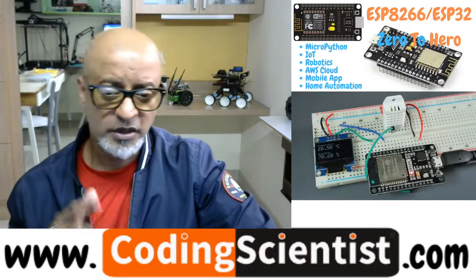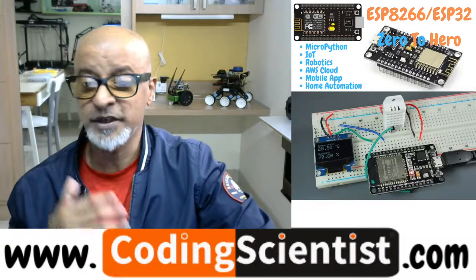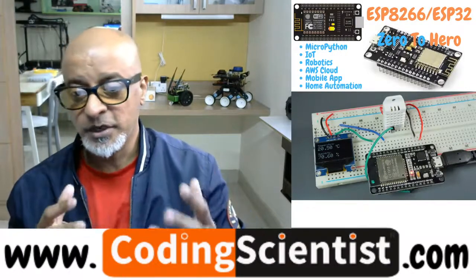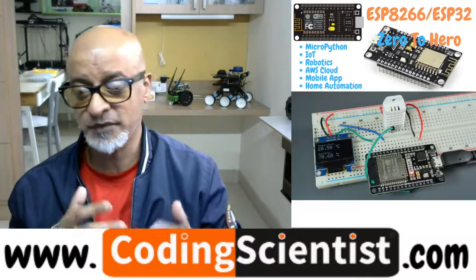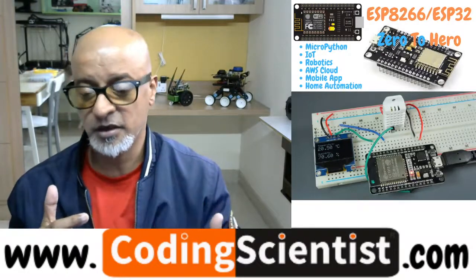So in this particular lesson you need to install three important libraries. Number one, the SSD1306, which we did already in the previous lesson, right? I showed you how to install it. And also the companion library for the SSD1306 OLED is GFX, which is basically for the graphics. So that's Adafruit underscore GFX. If you type it, you will get that library.